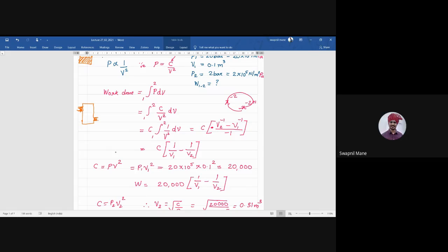Yes, sir. Then we applied what? Steady flow energy equation. In that case, Q minus W shaft work will be equal to delta KE plus delta PE plus delta H. Yes or no? And there was one more term which is called W flow work. You remember now? Yes, sir.